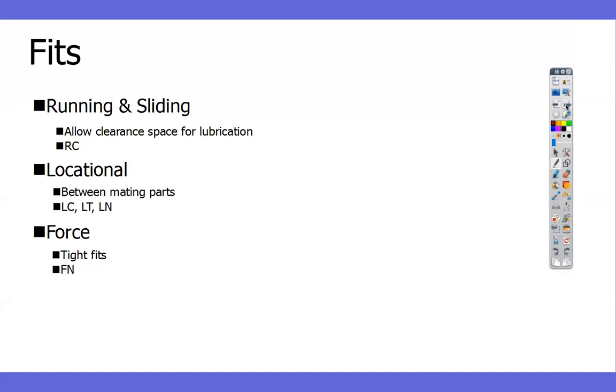There are three main types of fits. There's clearance fits, where things are always going to fit together. Here, I want that always to fit together, right? You have a hole that a bolt's going to go through. You want that hole to always be bigger than the bolt. Then we have things where we want them always to interfere. When you're pressing a bearing, you want the hole for the bearing to be a little bit smaller than the bearing. That way the bearing doesn't fall out, right? A little bit smaller. Other things, you're going to want it to be even smaller, so it's an even tighter fit. That way you can push them together and they stay together forever without having to add glue or weld or anything like that. And there are some things that can be either one. Okay?